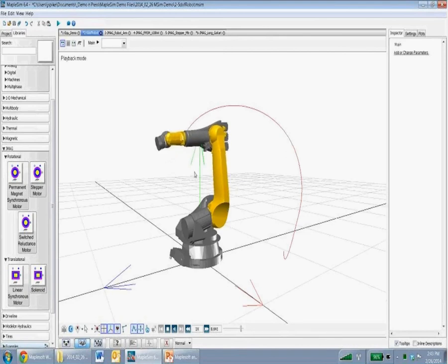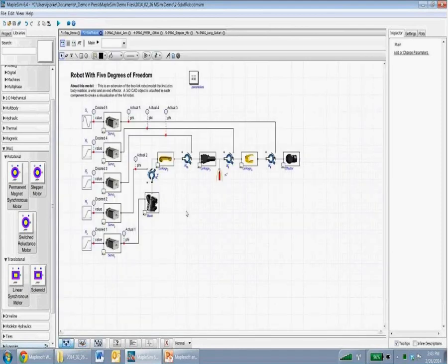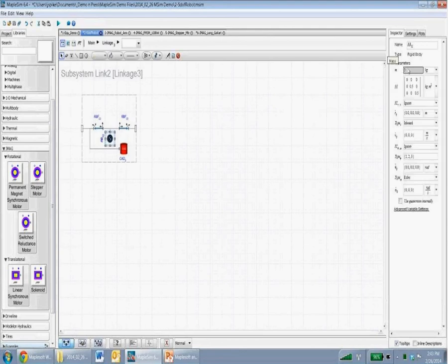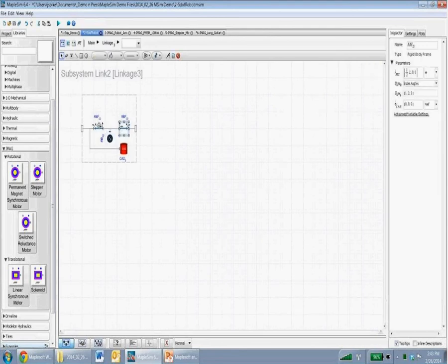When dealing with robotic modeling, a major component that drives how the overall robot dynamics occur is to control where the end effector is. Knowing the motor accuracy and how to properly control that is a major factor. This model was the development stage where we've done a basic servo motor. We've included the multi-body robot arm with the different joints, as you see here. And inside each of these arms, we can include information such as the mass and inertia properties, and translational offsets for the different link components, as well as CAD information.